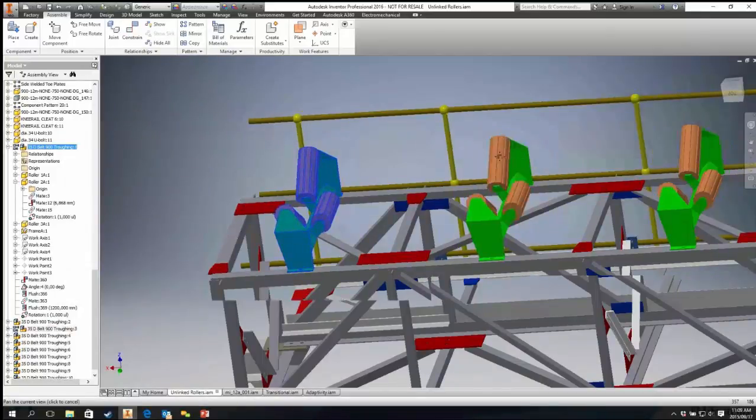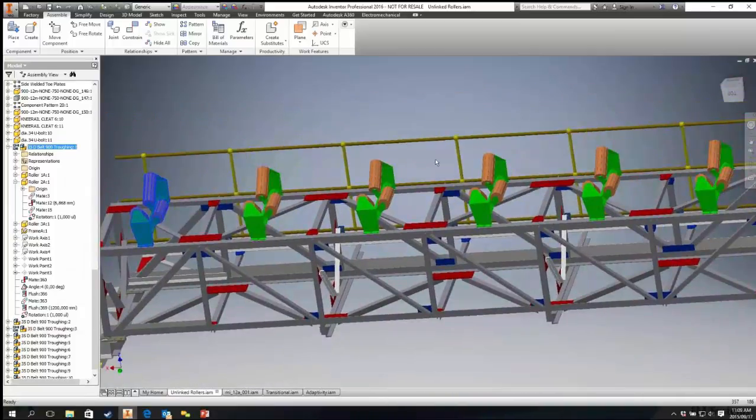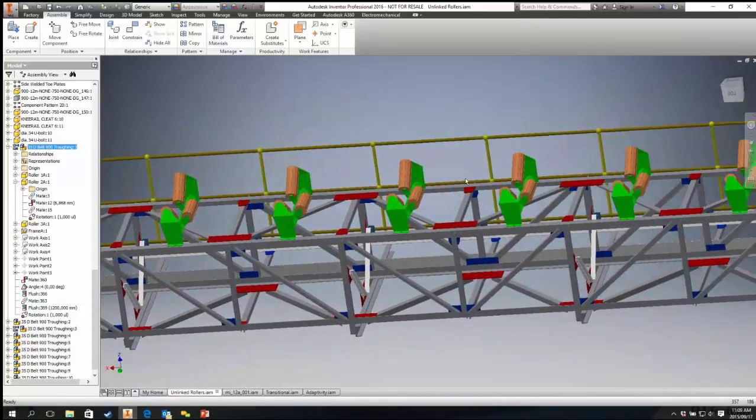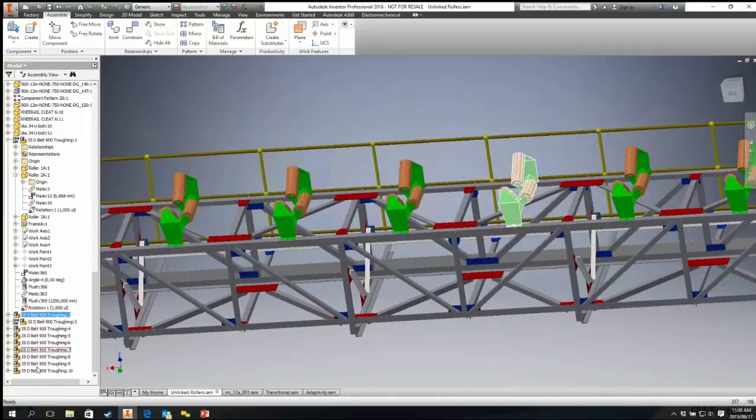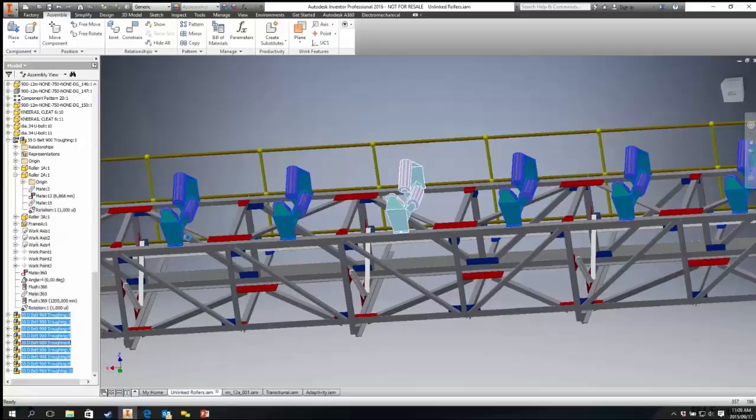And a quick way of doing this is just enabling the flexibility on each of them because they're not flexible yet. So I'm going to select this all the way down here and make sure that they're all flexible. And when I do that, now I can see individual ones rotate, any of them, and I'll see their wheels will move.